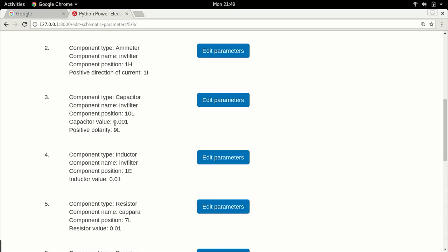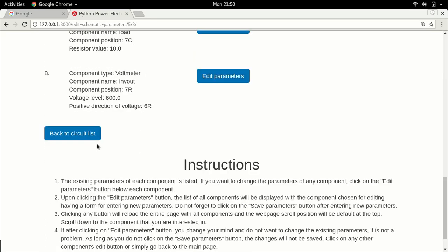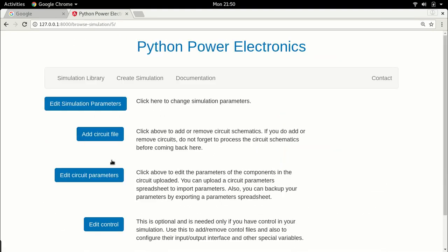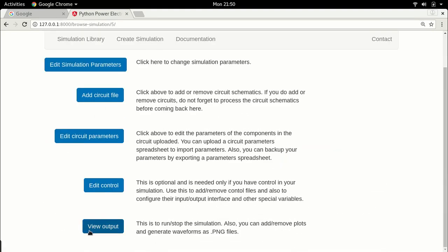Same thing with a capacitor. A 1 millifarad capacitor is a very large capacitor. Usually capacitor sizing is not as much of a constraint as inductor sizing. Any power supply designer is going to try to minimize the size of the inductor as much as possible, and this is way too large. Alright, but this is what is needed. If you want a smooth sinusoidal voltage, this is what you have to do. It's as simple as that.